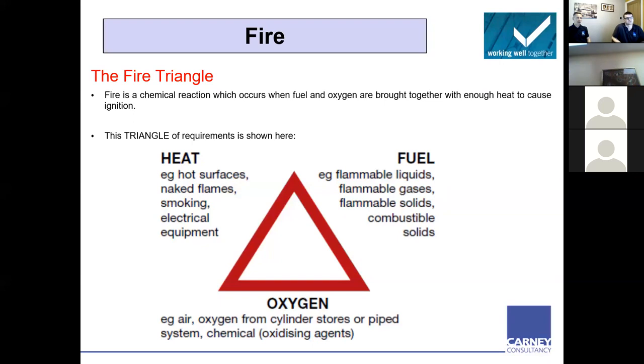If you do have an ignition source, what's on your site that's going to provide fuel? Cardboard packaging, quite easily. There's a lot of stuff gets delivered. Pallets, timbers, all are going to help provide fuel. But again, flammable gases, flammable liquids. I've seen plenty of times over the years on site, piles of pallets, and that's also where they keep the petrol for the generator or for the stihl saw. You've got fuel, all it takes is an ignition source.